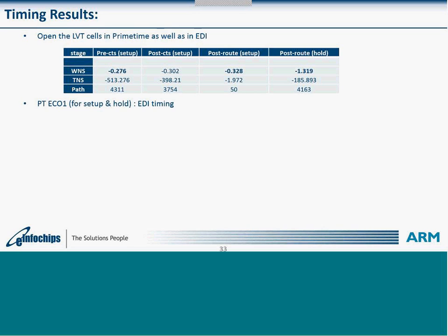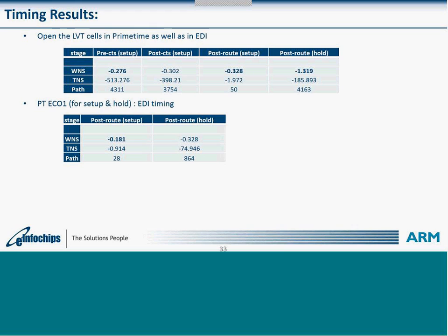After a couple of iterations of ECOs, we finally could close both setup and hold at 470 megahertz. In the journey of these timing STA fixes, we tried different experiments with different techniques, and got the best results. So yes, we could close it at 470 megahertz.